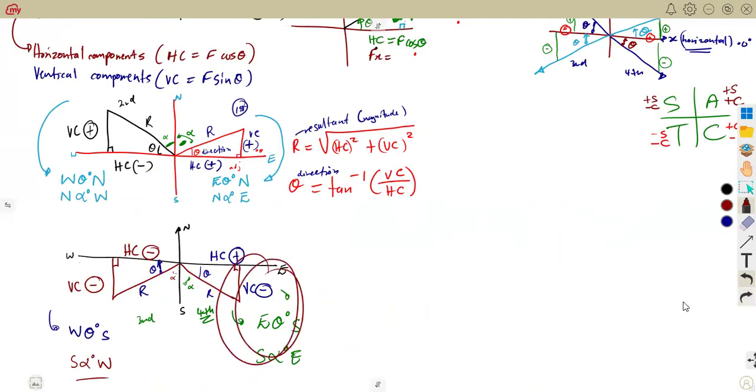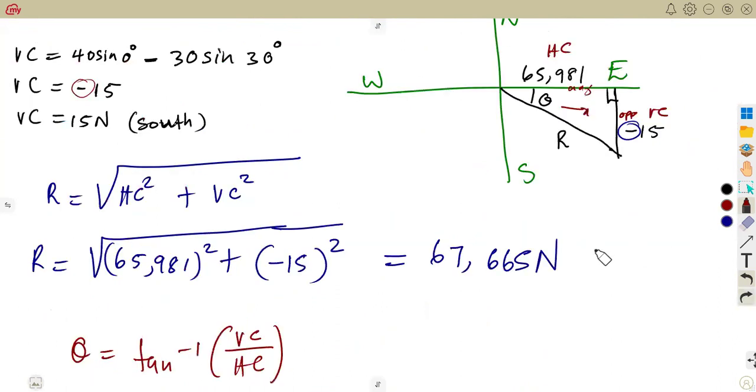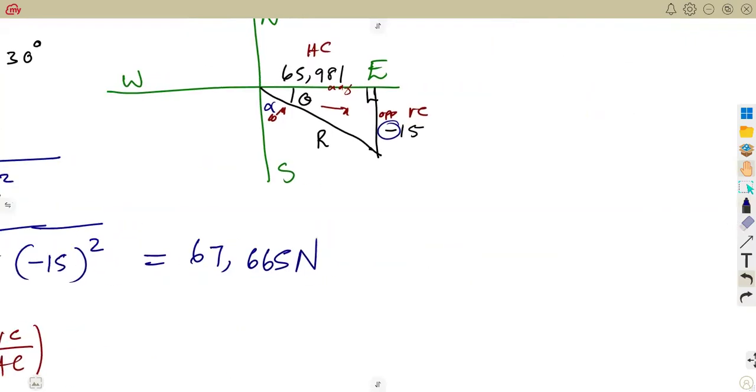The fourth quadrant here, it is either we are moving from east to the south or from the south to the east. If you are calculating south to the east, you must calculate the alpha, which is this angle that is in between there. If you want, you can calculate this angle that is in between, this alpha here, for the direction. So for you to calculate alpha, remember this is a quadrant divided into 4, guys. This is 90 degrees. So alpha can be calculated from 90 minus what? 90 minus theta. So meaning to say our alpha is 90 minus our theta.